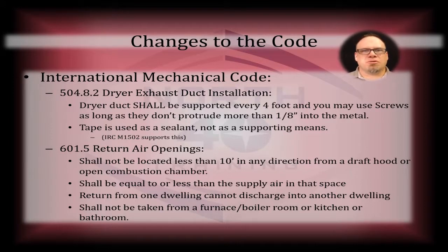And the reason you can't go through 1/8 of an inch is because of spindling. You've got a piece of screw sticking into the metal, and then the dryer lint and stuff starts to spindle around that screw, and all of a sudden now you've got a big ball of dryer lint in there that's potentially a fire hazard, and also that's causing an obstruction to the airflow. So those kinds of things make a difference. If he was going to allow that, the inspector speaking to me said, think about that. The screws you're going to use are probably zip screws, using a 1/4-inch chuck and a drill.